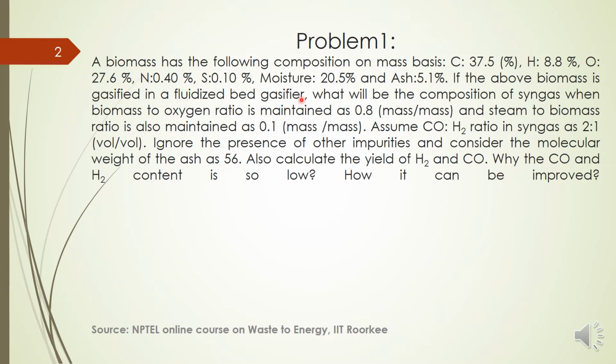So in typical problems we have to solve step by step. So first we know that we have to find out the molecular formula of biomass from this mass basis data given. The first step is we have to find out the molecular formula of biomass. Then second step is we have to write the chemical equation of gasification based on the data given.